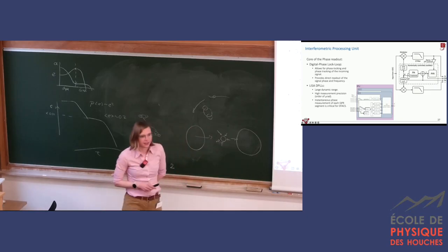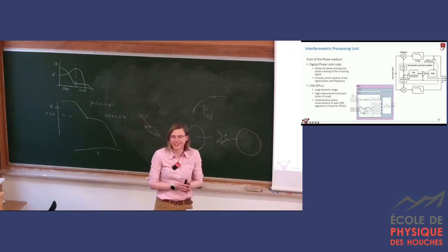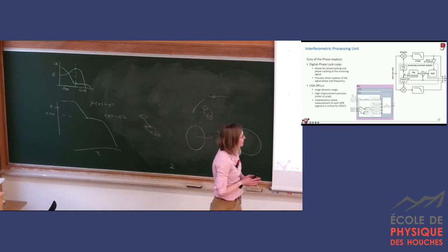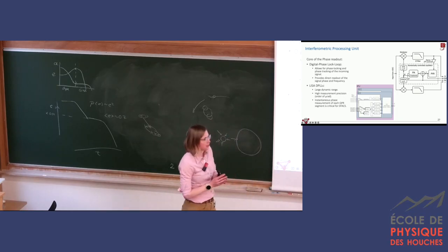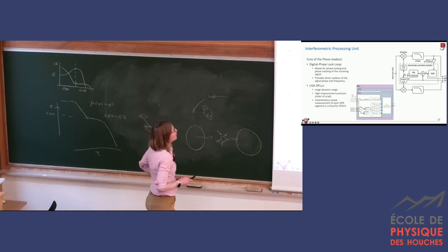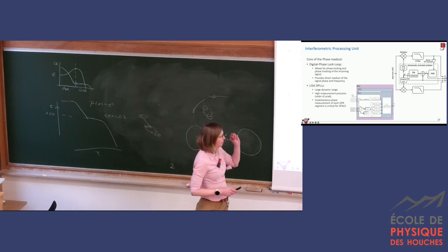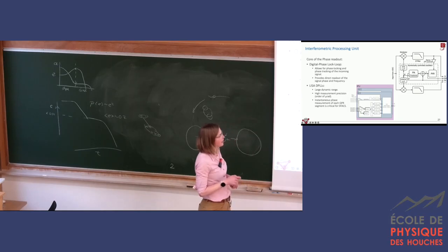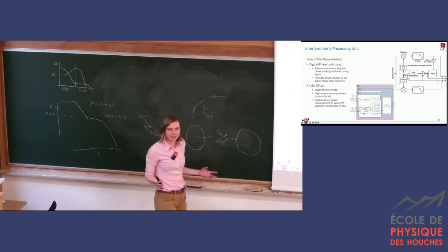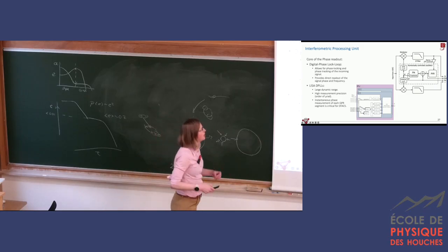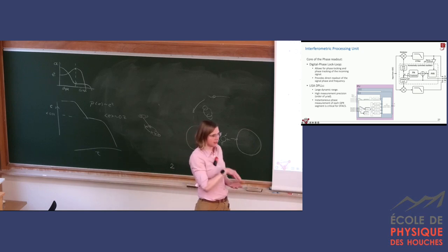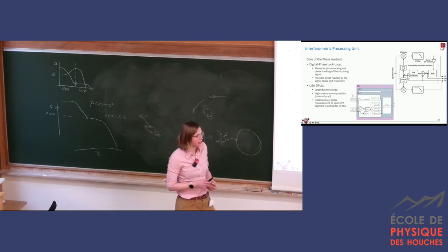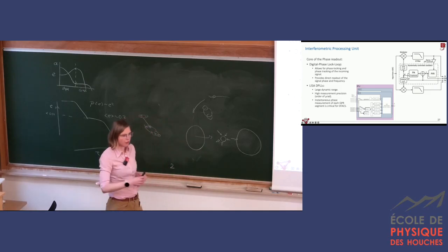The one thing I would like you to understand is the basics of how a phasemeter works. So bear with me, because there's going to be a little bit of math as well, but very, very simple. The core of the backend electronics, or the phase extraction system, is the phase lock loop. Phase lock loops are pretty standard things that are used all over the place. We have a digital phase lock loop because it's in the digital land of the phasemeter. And the non-standard thing about it is what I already mentioned: it has to cover a very large dynamic range.